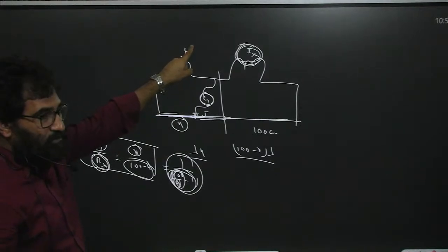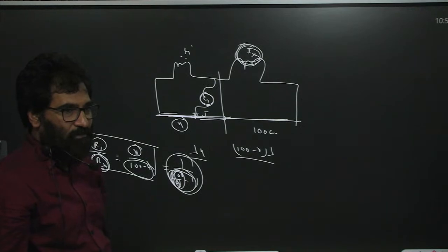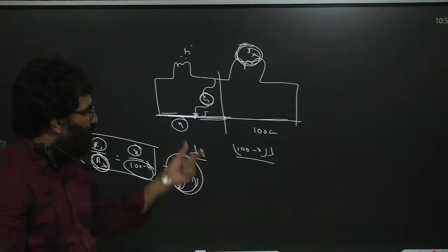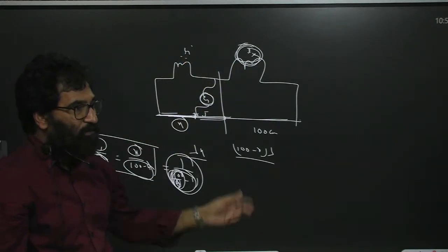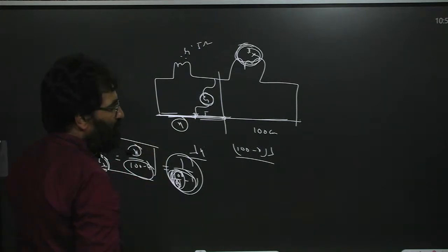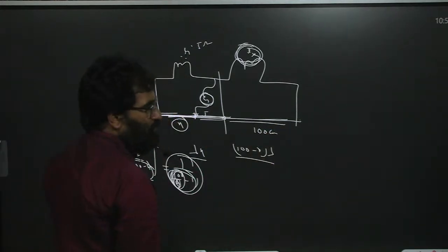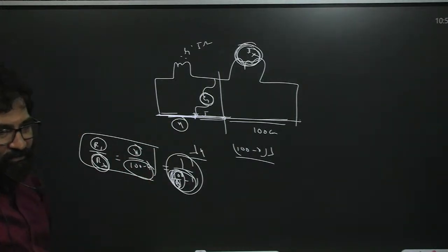So this is 5 ohms. This unknown resistance, balancing on this 49. The 49 is less than 50. So this should be more than 5 ohms. You keep the answer, this is 5 ohms. So balance on this 49, this is 51. So definitely this resistance should be more than this. So this is 5.1 something like that.